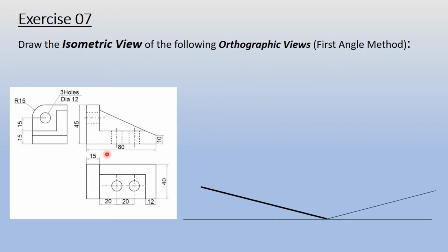See that this is the front view. First I will try to, this is a line here, 80 mm. So this portion I have drawn from this area. Like this, there is no portion in here, but I have drawn it completely here, indicating this portion from the front view. And I'm drawing this here because there should be one right hand side view. That is why I'm drawing the front view here. And this is the portion. And this width should be taken from the right hand side view.